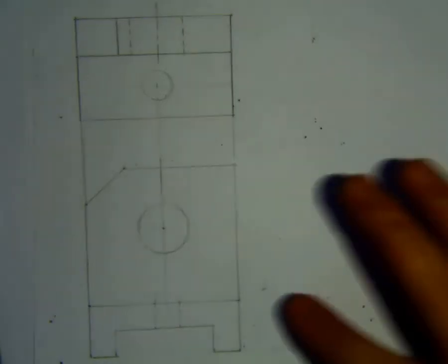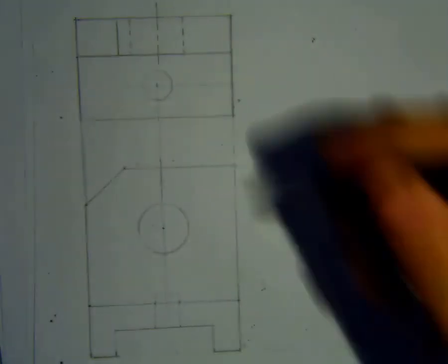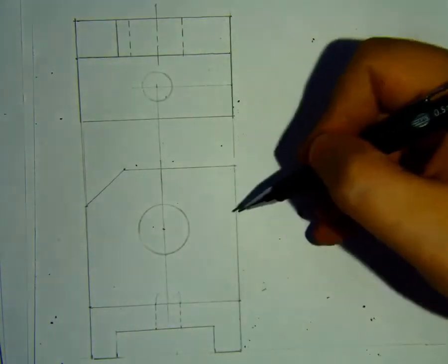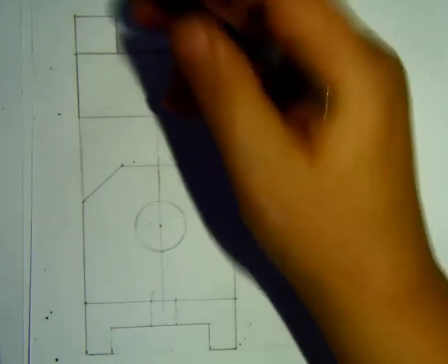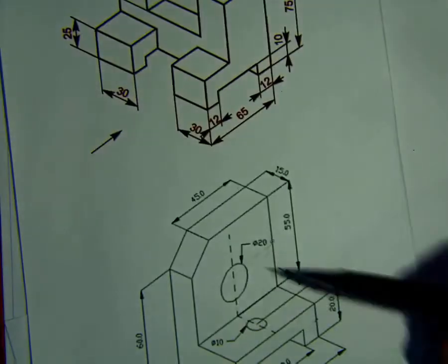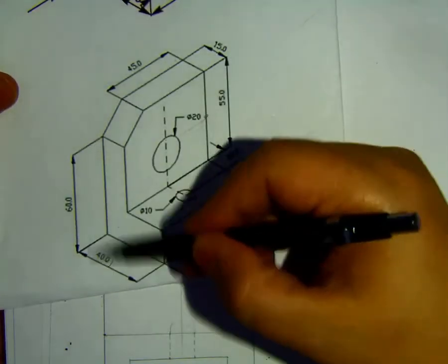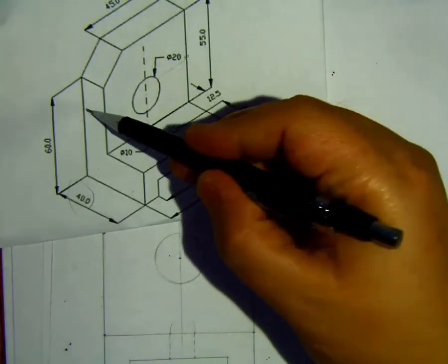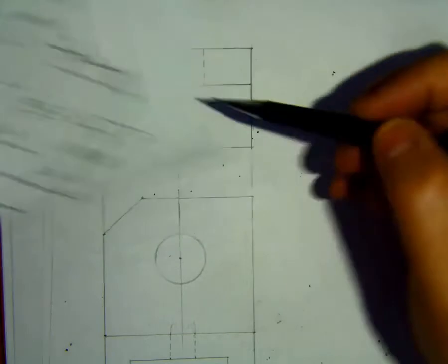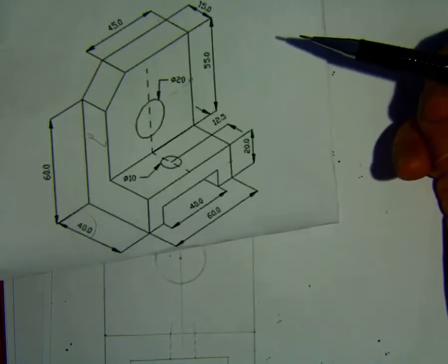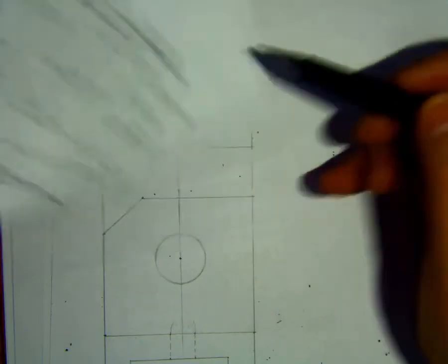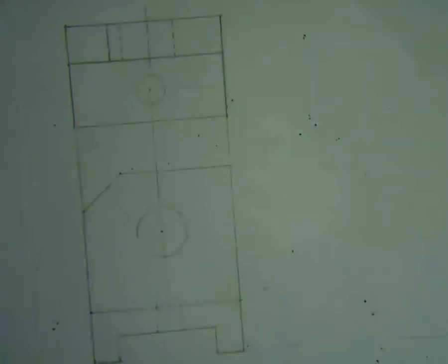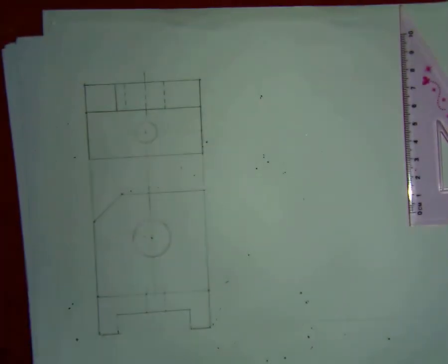Now I will draw the right side view. Why do I need the right side view? For this depth, for the hole, for this value from here to here. I need to show 40 degrees. Can I show it in the drawing here? Yes, I can show it from here to here. To show this value, 15, which is the same. Can I show it here? Yes. And the hole, I can see the hole here. I don't need the right side view. Then I can apply dimensions on the given views.